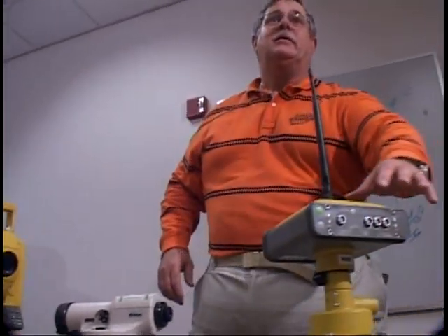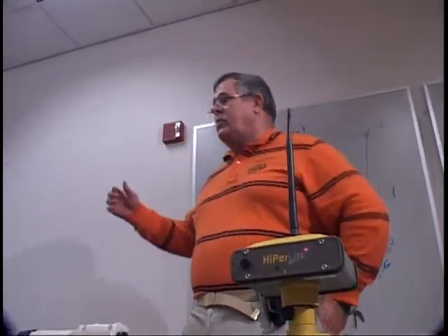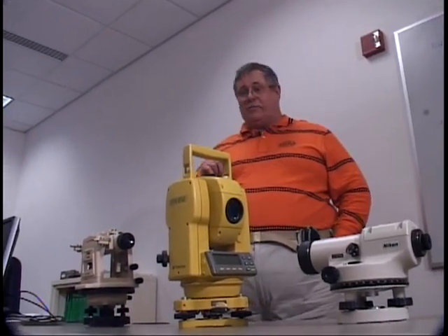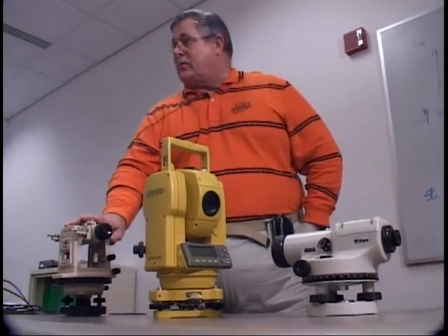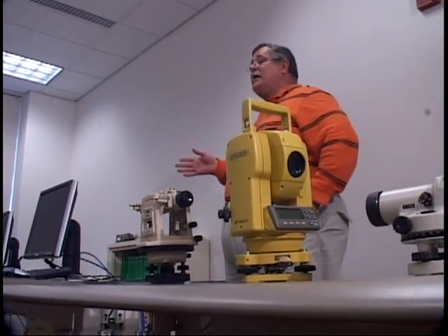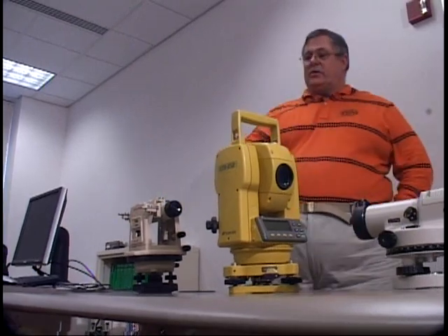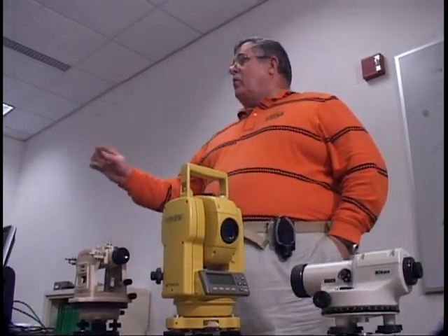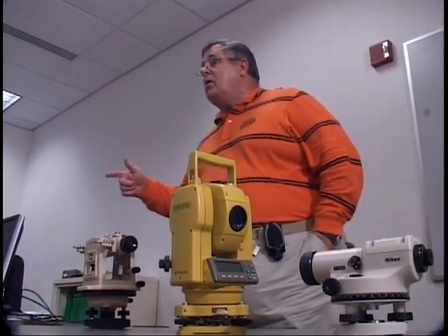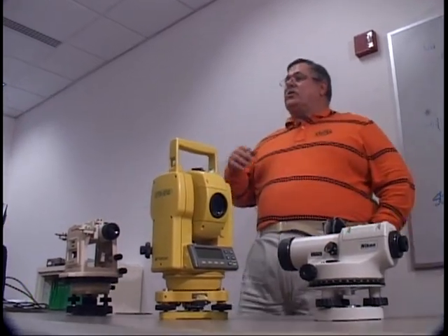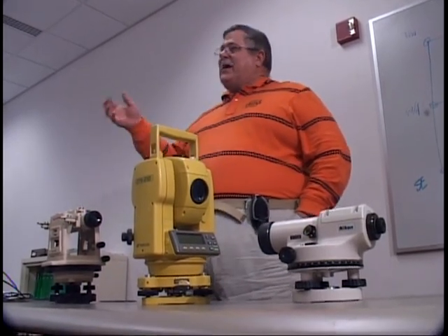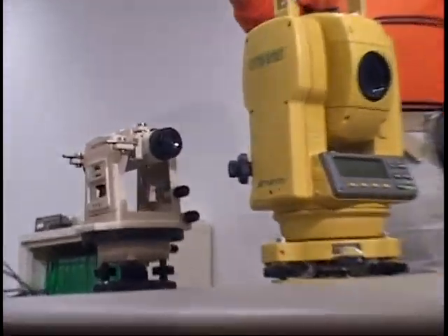Okay, are we ready? Okay, guys. During the course of this class, these are some of the surveying instruments we're going to use, not all of them. But this is a transit or theodolite. It measures both horizontal and vertical angles. It does not measure distance. When you use this type of surveying instrument, in order to get distance, you can either measure the distance by using a surveyor's tape or chain, or you can measure distance by using a stadia rod. And I'll explain that later on in a class on how to measure distance by stadia. It's kind of a methodology that has gone by the wayside.